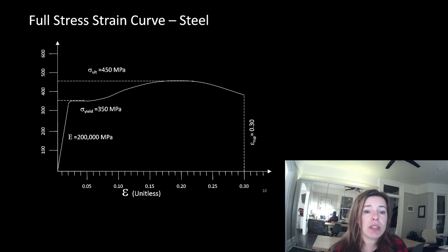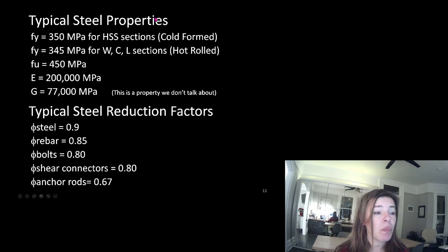Damage to finishes on a beam that's deflected too much is something different. It's still safe for life support, so you could stand on it, you've just destroyed your drywall. But if you've got that really harsh, extreme bending on a steel member, it's because it's yielded.